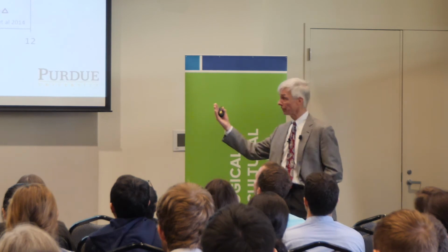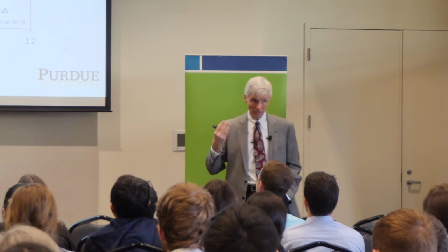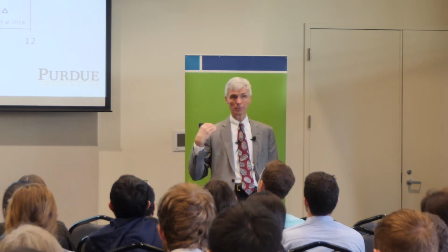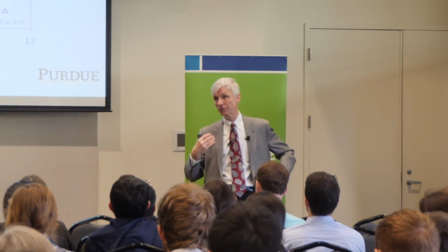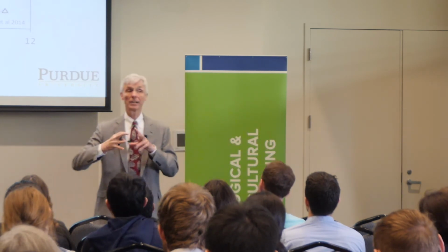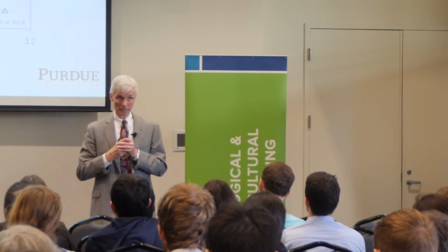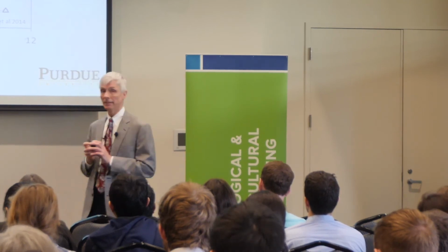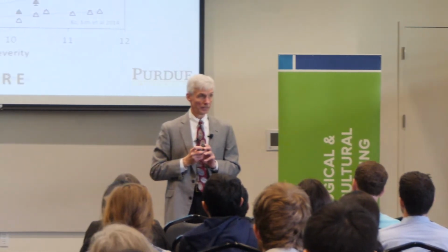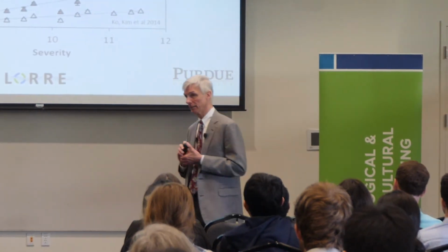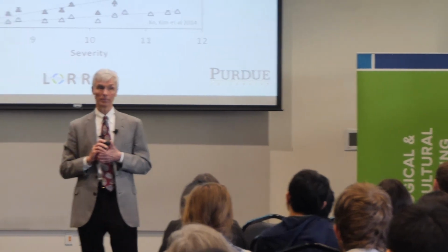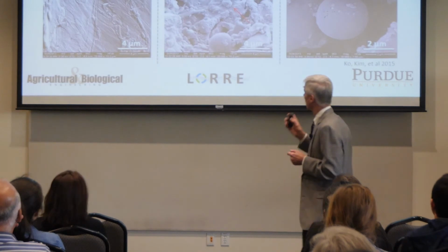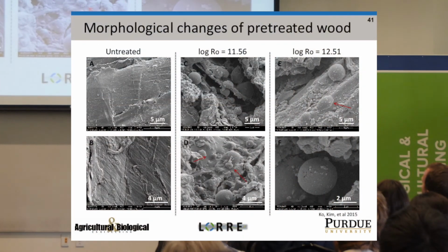And we would run the hydrolysis for a long time, 5 days, it didn't change. The severity is the time and temperature we use for pretreatment. So higher severity means we've been rougher on the cellulose, gotten more lignin out. So if you look at this, at least to me, it seemed, why should it be that there's such a huge difference? Unless we were titrating some sort of activity into the biomass material. Now think about that. Well, it turns out, here's just some scanning electron micrographs.